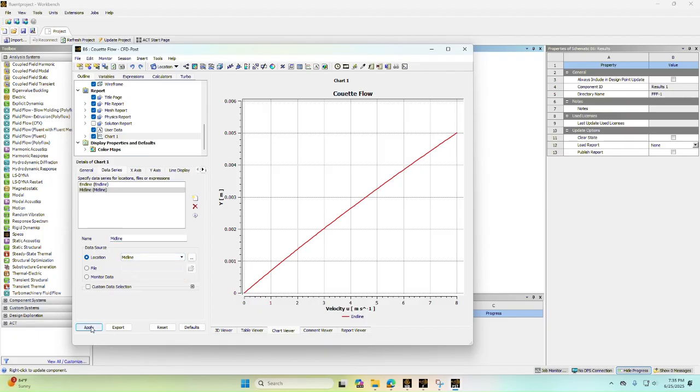As you can see, if I apply the midline, it's right there. And doing the calculation, the Reynolds number comes out to, yeah, so we get 1200 for our Reynolds number for these specific parameters, and that is why we get such a nice line here. Same flow with our end line and midline.